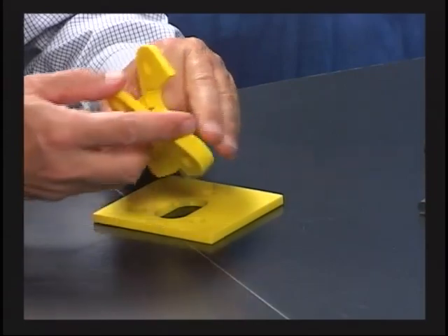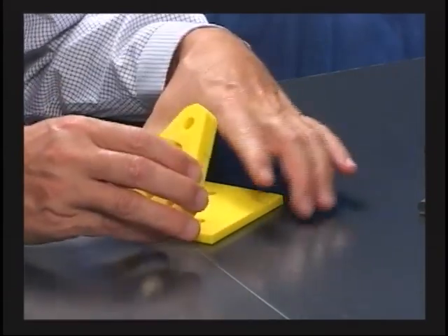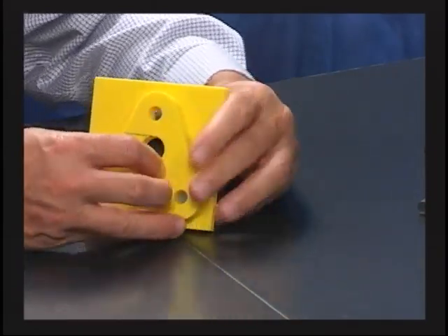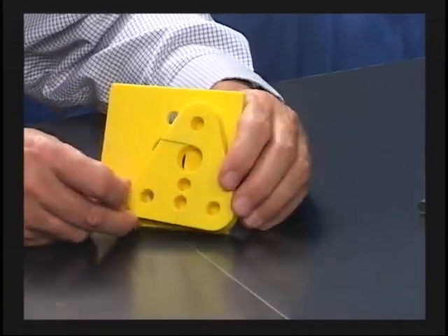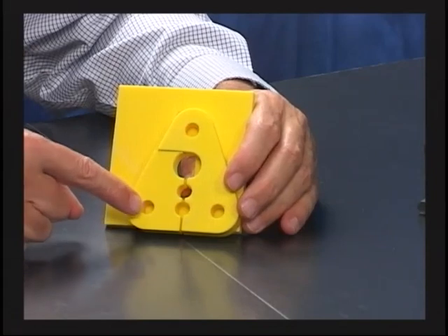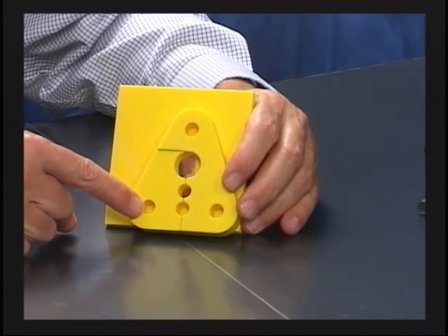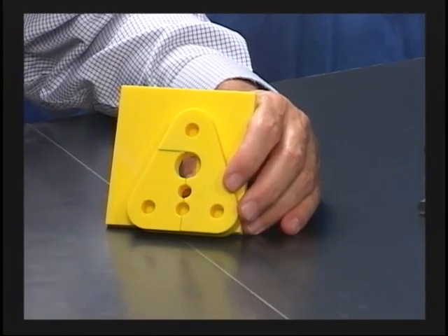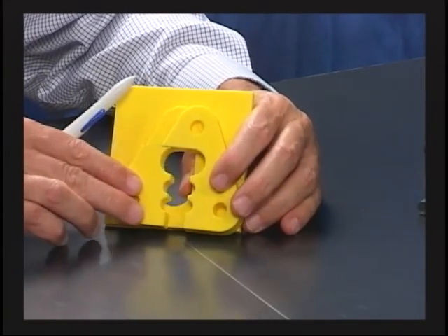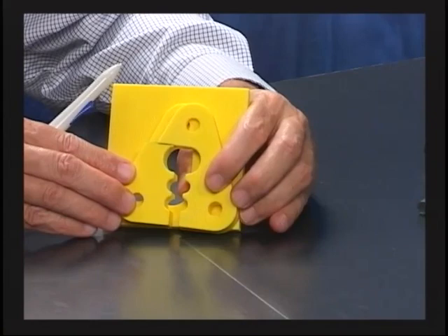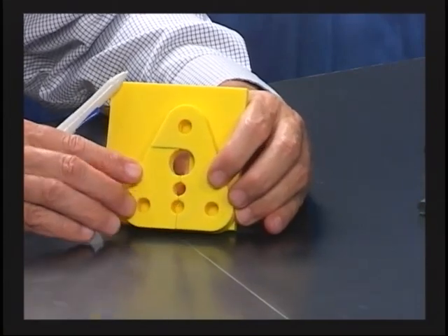Now, I see sometimes people say, well, why not just pick the holes as your datums? And I suppose you could. You could pick the holes as datums, and then locate the surfaces. But the problem is, if I pick the holes as datum and call those holes 0, then I'm going to have to tell you how much this face can be off. And I don't want this face to be off. I want the faces to come up tight. That's where they mount. They mount up tight against those faces.